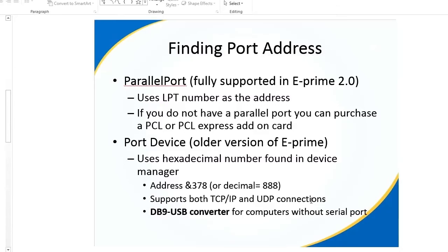It is vital that serial to USB cables use the latest drivers available. A lot of times users will use this DB9 USB converter and then have some trouble connecting their response box or their FOBRS, their button response systems. The troubleshooting we suggest is to go to the site of the cable manufacturer and get the latest drivers. Once they install or update to the latest drivers, the problem is taken care of. So you would visit each cable manufacturer's website. You could also try Windows Update; sometimes Windows Update will resolve any connection issues you may have with those drivers.